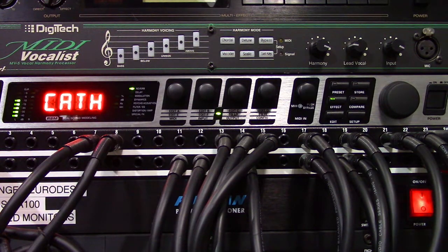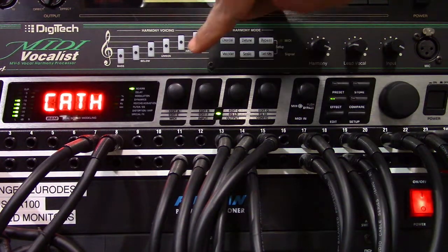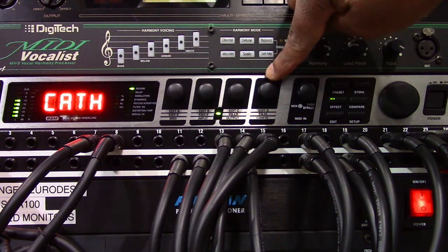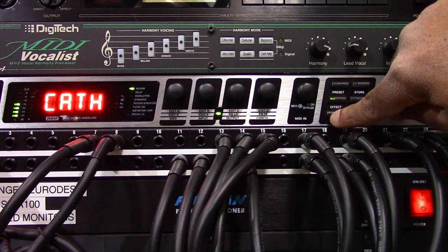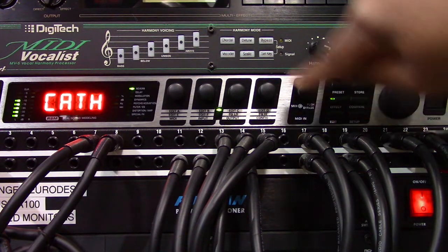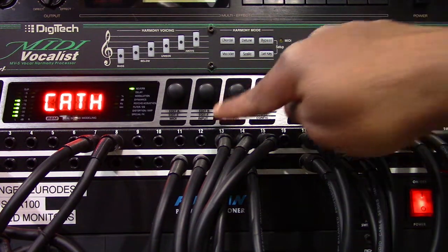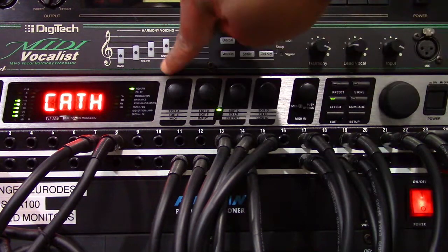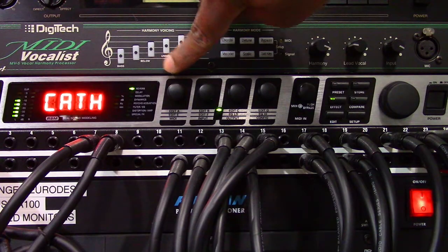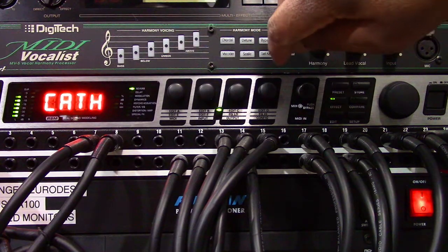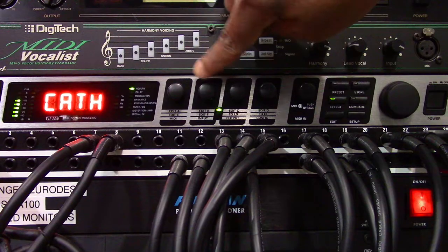Every preset in the FX2000 allows you to edit at least 4 effects parameters. The edit LED chain indicates which parameters are adjusted by the 4 edit controls. If the top LED is lit, the first edit control knob controls parameter edit A. The second edit control controls edit B.